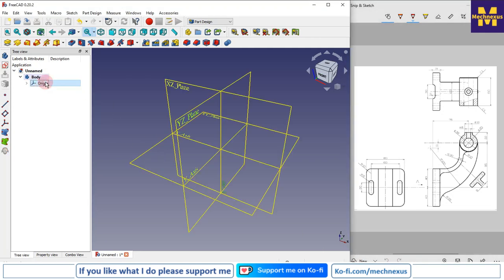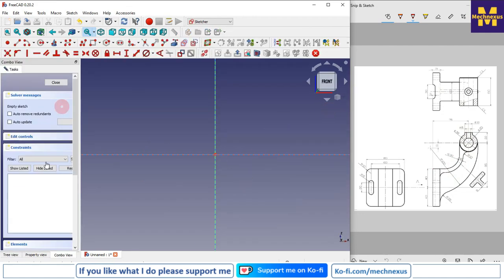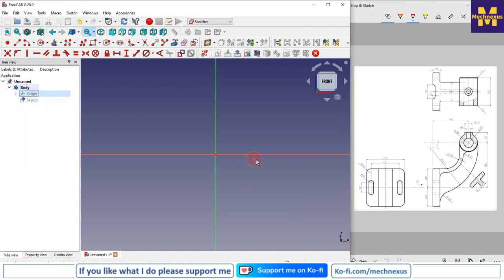I will turn on my origin plane, and as per our part view, we will design our base sketch on this XZ plane and then extrude it with a length. Then we will make this profile, and after that the circular profile and this profile. So first select the XZ plane and create a sketch. Now I will turn off my origin plane.